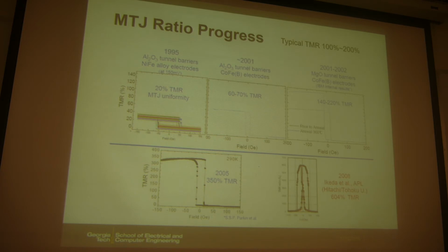So it's quite challenging. Second one is because on-off ratio is only 2, so essentially this is like a binary memory. Very hard to achieve multi-level cell. Because in principle, if you want to achieve multi-level cell, you will insert the resistance levels between the very on and the very off states. But in this case, the very on and the very off actually only differ by two times. So it's very hard to insert additional steps between those on and off.